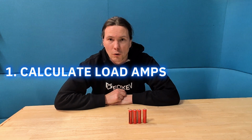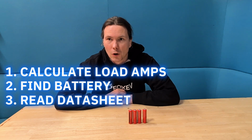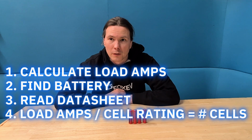So you calculate the draw of your load, you find a cell and its data sheet. In the data sheet, you locate the discharge rate and you divide the load requirement by the cell rate to figure out how many you've got in parallel. You also have to put enough in series. Cool. I ran you through a quick example here, and I didn't give you an exact answer, but hopefully this helped to sharpen your mind towards what kind of questions you need to answer when you're designing your battery pack.